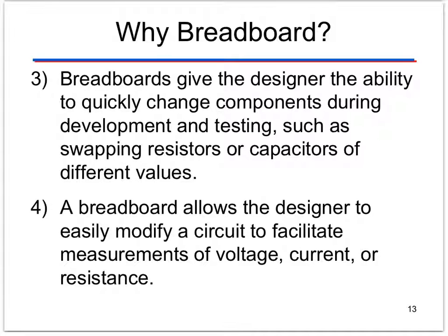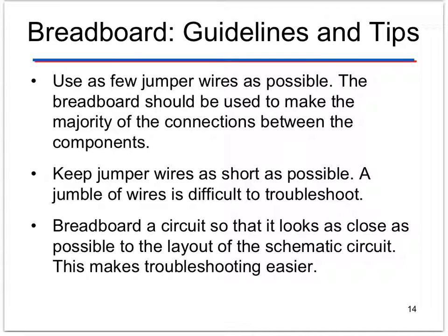Why also breadboard? Well, breadboard gives the designer ability to make quick changes to components, swap out capacitors or resistors. But a breadboard also allows the designer to easily modify the circuit to facilitate measurements of voltage, currents, or resistance. So it basically allows you to make changes. That's why we breadboard. So, let's get some guidelines and tips.